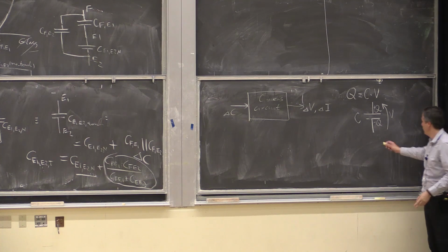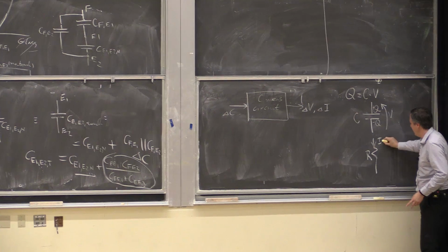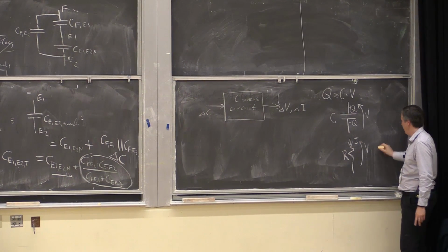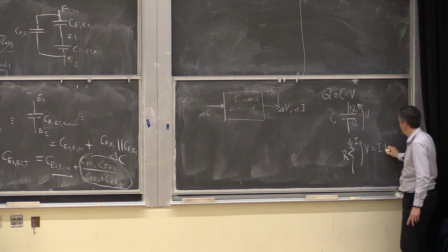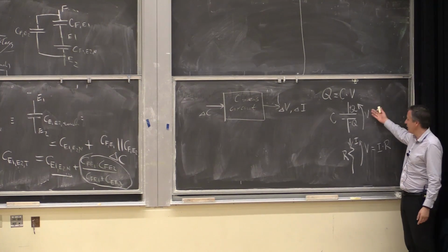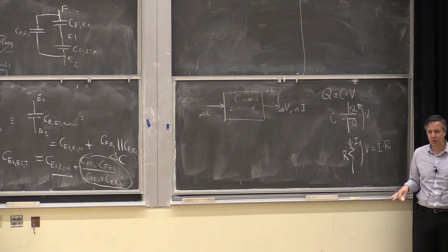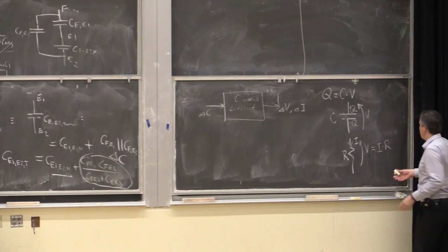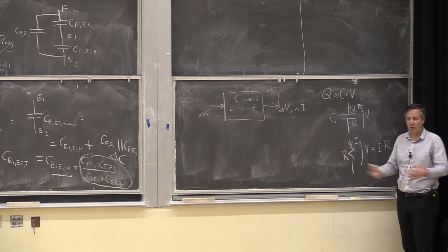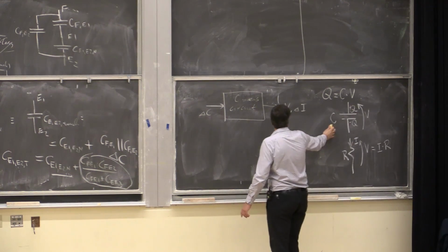Like the passive convention, in Ohm's law we had an R, there was a current I, and then a voltage V. And voltage V was I times R, but only in this condition, where the current flows into the plus orientation of the voltage. Same here. And you'll see this is actually key. If you forget this in capacitors, you're not going to be able to do any design. But if you remember it, it will be very easy. These are basically the two conventions that will solve all the circuits that you've done so far very easily. So just remember them.